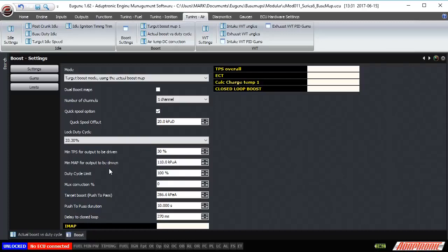And once you've done that, then your table's filled out. You don't need to sit there and adjust everything. Now after the ECU has the base duty cycle, which it's interpolated or reverse interpolated from one of those two tables depending on which mode you've got selected, the air temperature compensation duty cycle is applied.